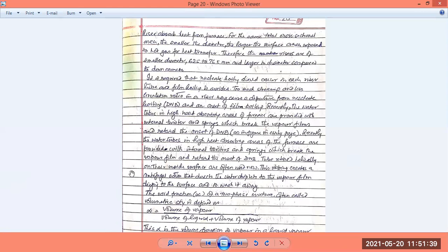So what is going on? What is told here is how the saturated water that comes from the downcomer should boil inside the riser itself. We should prefer nucleate boiling, and film boiling over each riser tube is supposed to be avoided.